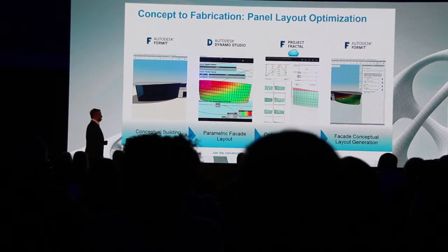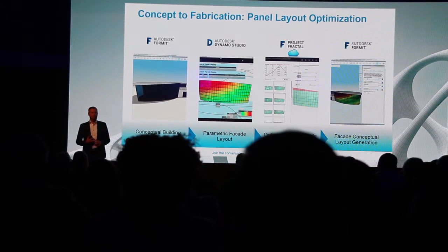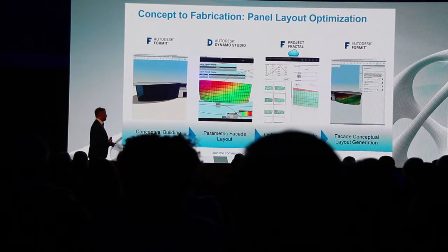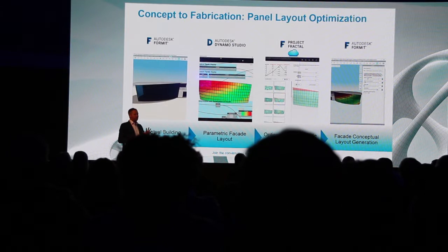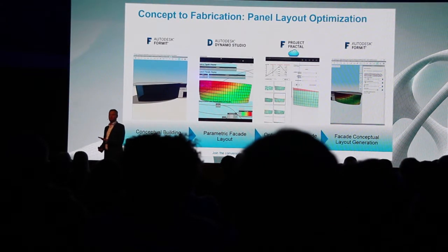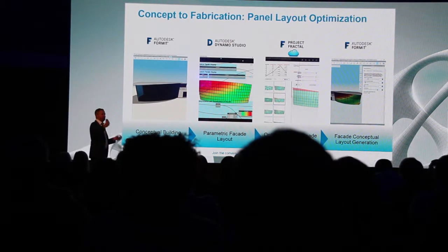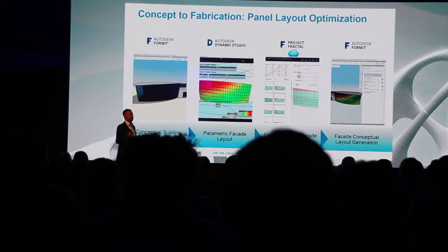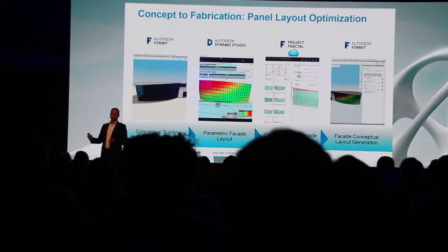Now, we can parameterize that layout without Revit functions because I want to analyze all these panels against a few specific problems. One of the problems is, of course, is it torsed, yes or no? Do we have any torsion in that panel, or is it perfectly flat? We call this planar deviation. So if you have 3 points and you want to know if these 3 points are in the same plane, 3 points are always in the same plane. 4 points are not necessarily always in the same plane.